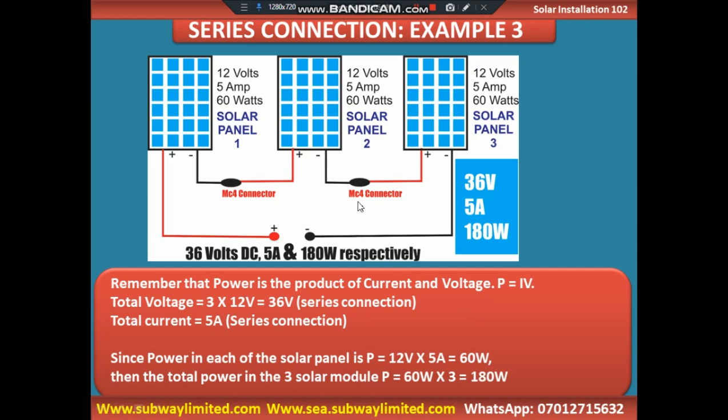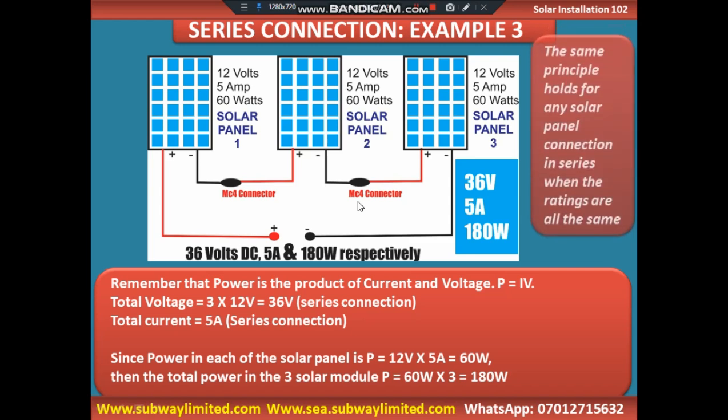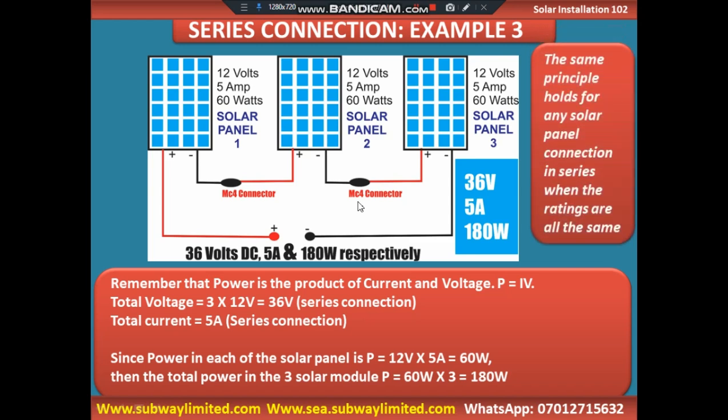That is how you get to understand how to connect solar panels in series. The same principle holds for any solar panel connection in series when the ratings are the same. Even if you have 1,000 solar panels and you connect them in series, the voltage will always increase, but the voltage will be too much for you to send to a component.